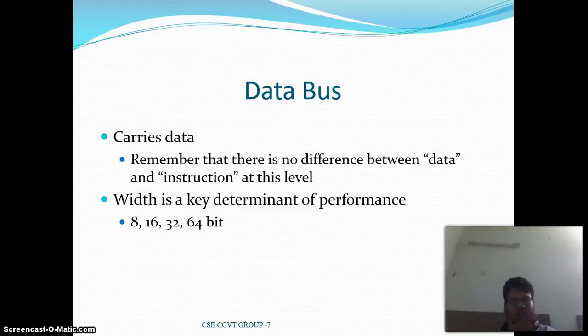The bus structure consists of three lines. First is the data lines, which provide a path between system modules. These lines are known as data bus lines. Remember that these data bus lines typically consist of 8, 16 or 32 separate lines. The number of lines is referred to as the width of the data bus. Each line carries only one bit at a time, so the number of lines determines how many bits can be transferred at a time. This increases the overall system performance which we need.